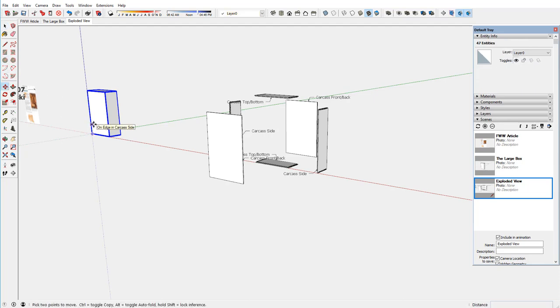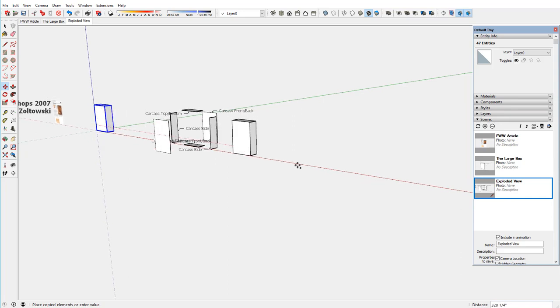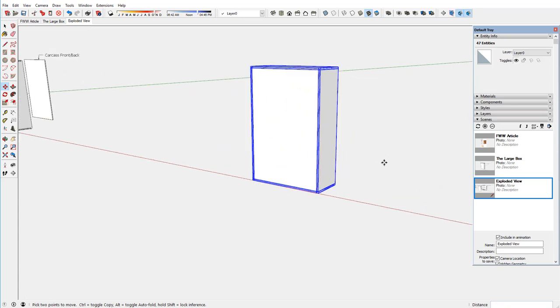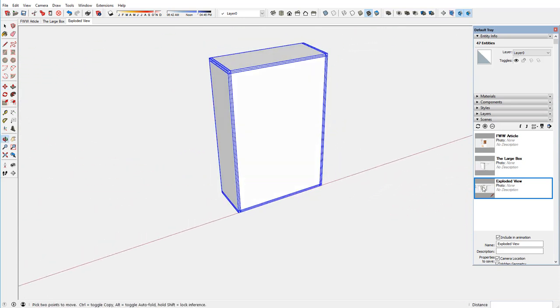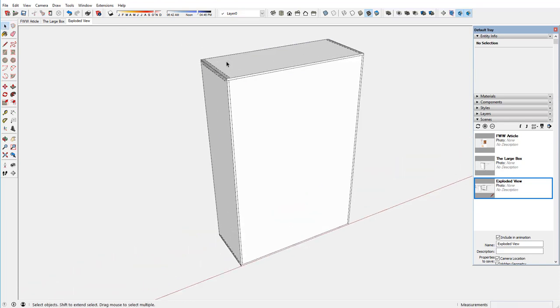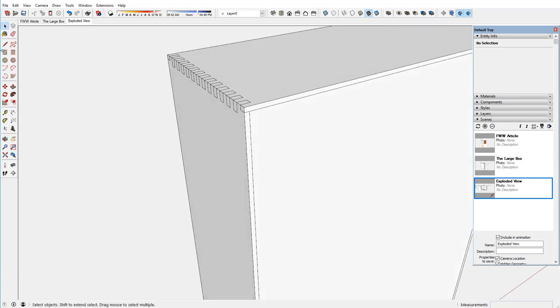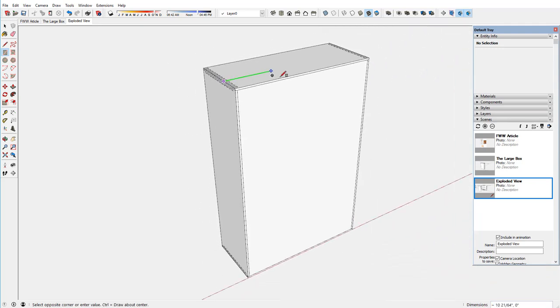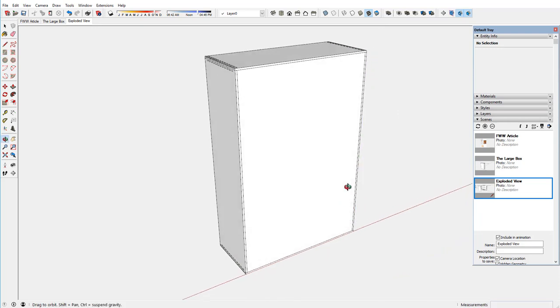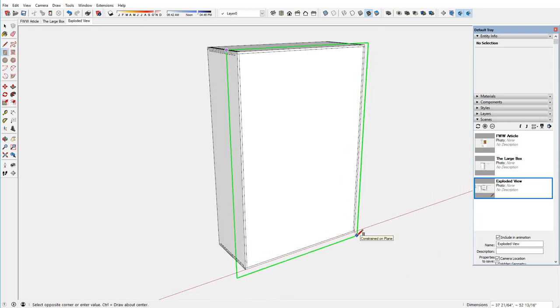reorganized into the final toolbox construction, and that means that this big box is going to be sliced in a table saw, for example, to create the front doors. And in SketchUp, it would be good to be able to simulate that shop work. So at first you build according to the overall components, and now you want to have a SketchUp model with the final components of the toolbox.